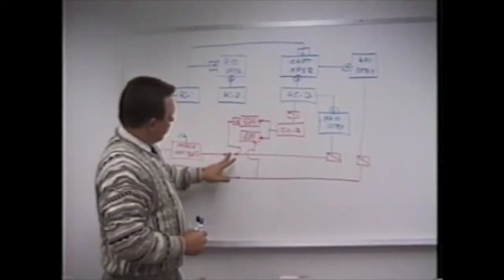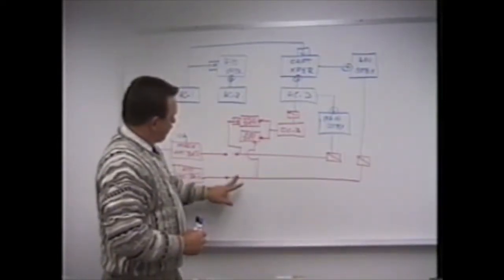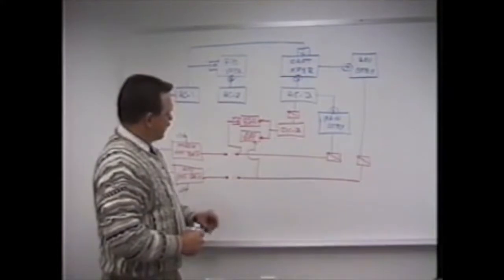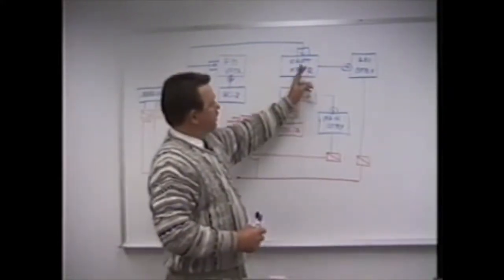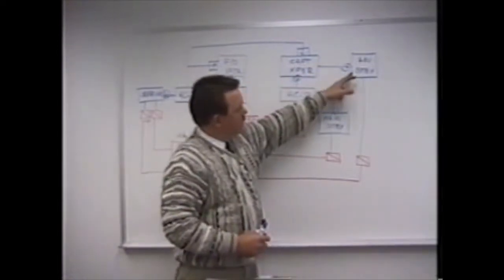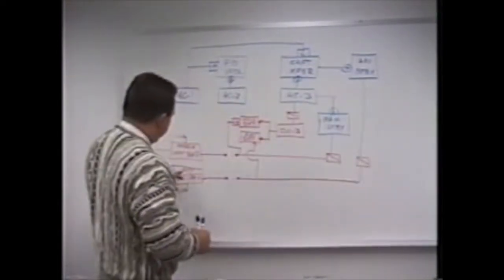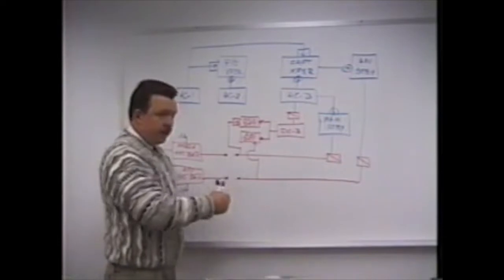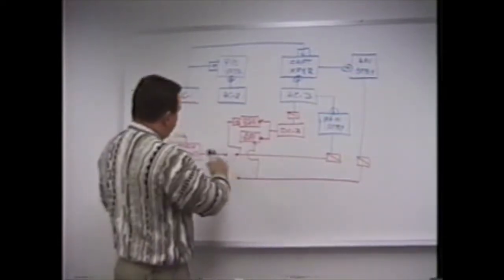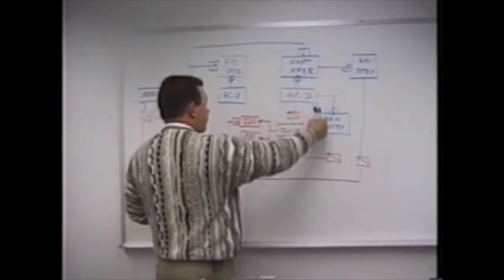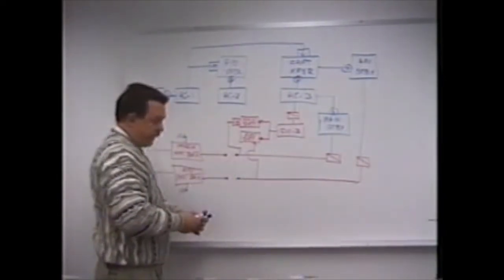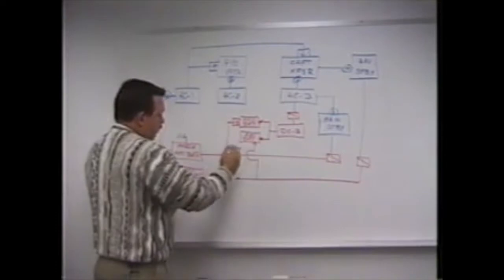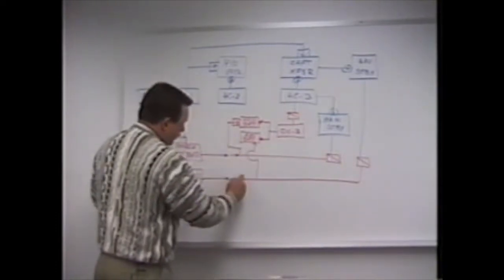In the unlikely event the battery switch was to wind up in the off position for some reason, this would not affect the system. However, if a failure was to occur, such as losing the captain's transfer, APU standby would go looking for the APU hot battery bus, but with the battery switch open, the transfer cannot occur. Likewise, if the main standby was to lose AC bus 3, it would go looking for the main hot battery bus, and the transfer could not occur. So, normal operations, we keep the battery switch closed.